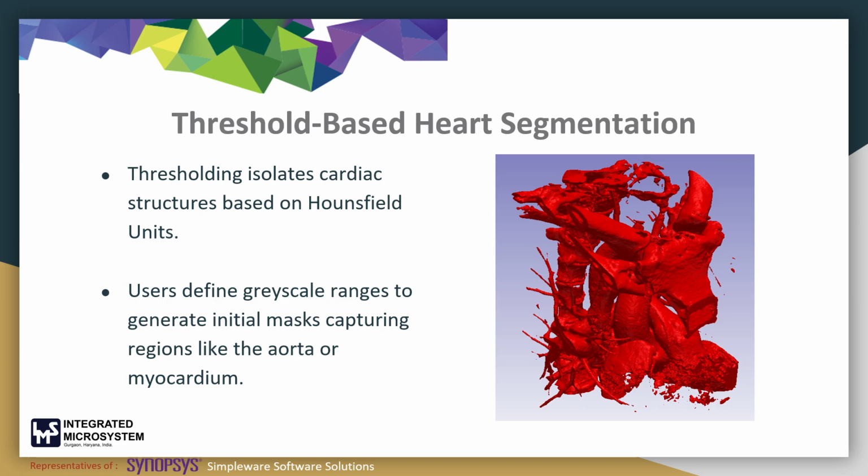Overall, threshold-based segmentation in Simpleware provides an efficient, user-friendly way to gauge the initial mask of the heart and vasculature. It's especially effective when paired with optimized grayscale settings and pre-processing filters, laying the groundwork for precise anatomical modeling and simulations.